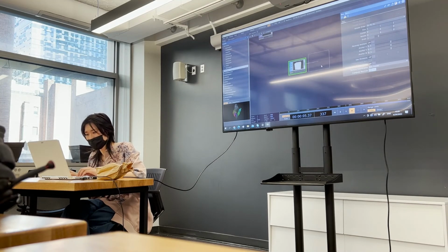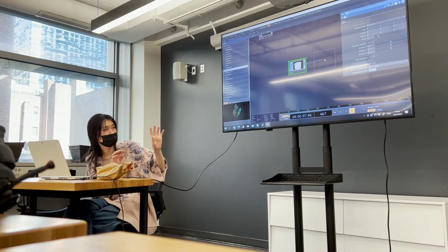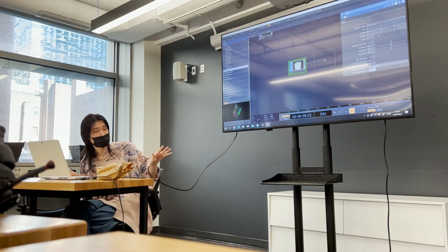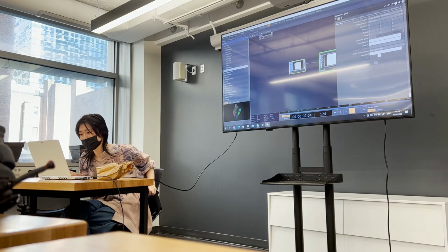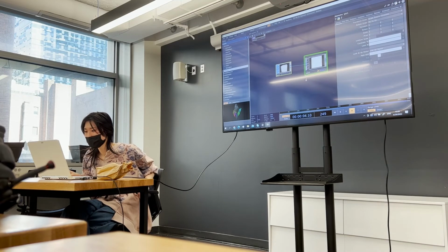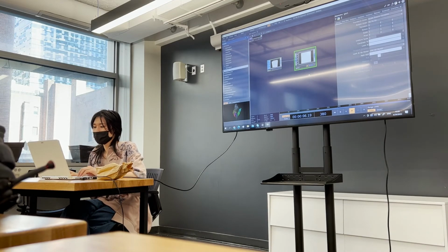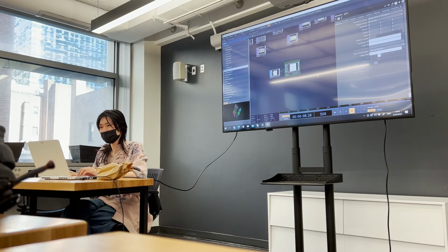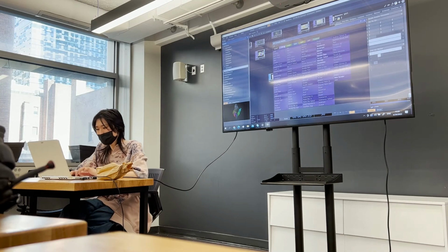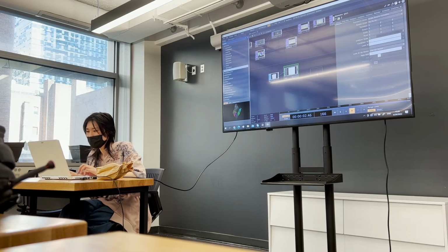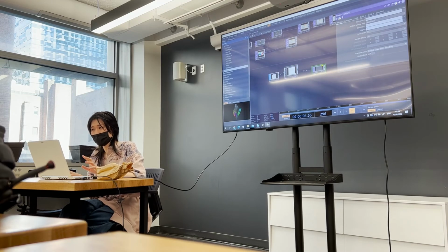And you right click on it. This time you have to right click on the output of the SOP to create this geometry, or you wouldn't have this input. So there's a geometry. The reason why you put it into a COMP is because there is a TOP called Render. And that's the thing that renders the 3D geometry.